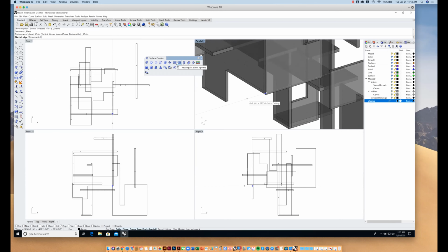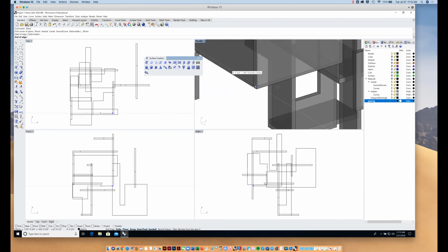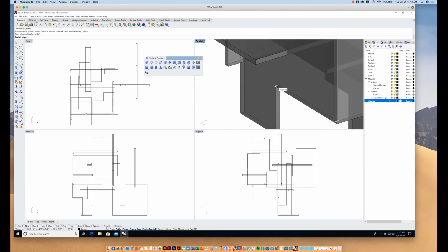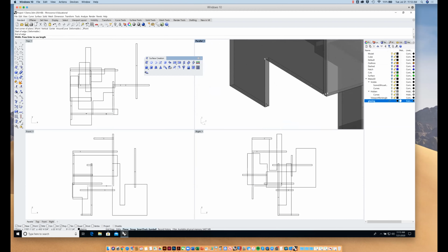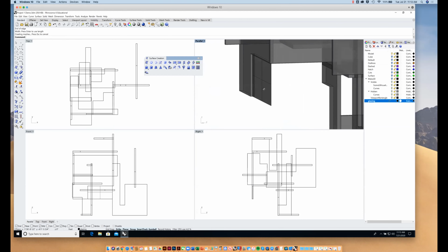So in this case, I'm just gonna need to set 3 points in space to create a plane. I'm gonna go ahead and turn midpoints on my O snaps, my object snaps down here. And I'm gonna try to snap to this midpoint and snap to this midpoint and snap to this midpoint. Now I have a perpendicular plane, okay?